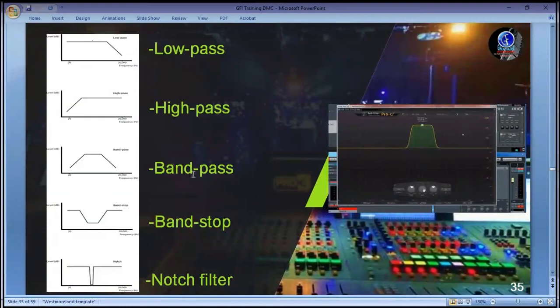It means that you are going to have your high frequency, your mid frequency, and your low frequency. So these three, low pass, high pass, and band pass, can be used to achieve your three-way tri-amp system for crossover in a digital mixing console. So I may not be cracking my head looking for speaker management to achieve this, because my digital mixer will do that for me.